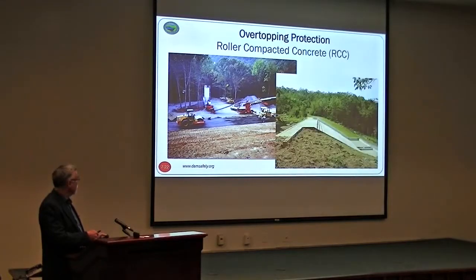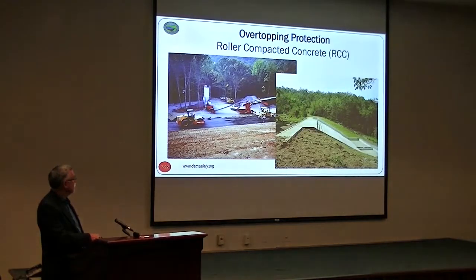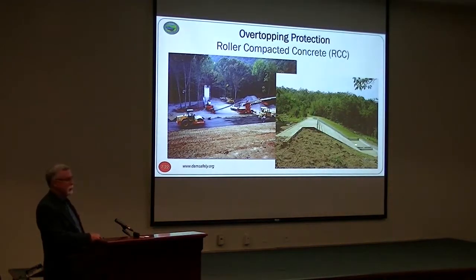You don't have to wait for it. You want to do them as fast as you can. And at the end of it, here's one. Generally, it looks like a series of steps, 1 or 2 foot high steps. So here you have a dam, and you've got some auxiliary spillway over the dam. So those spillways generally won't operate through a 50 or 100-year storm. So they may never operate for the life of the dam, but they're there for that big flood event.